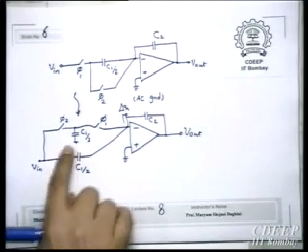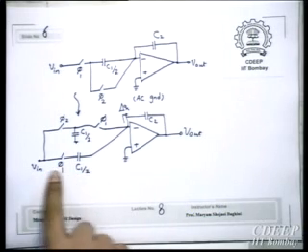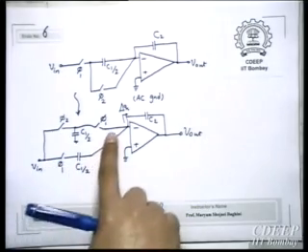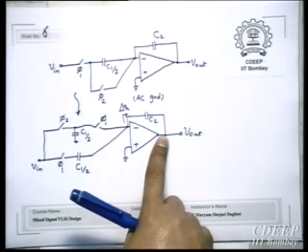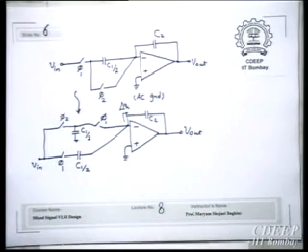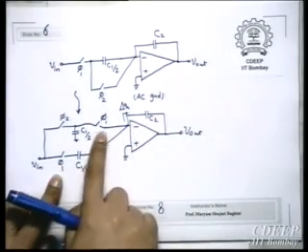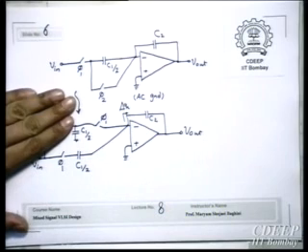Yeah. This one. Why can't we have a similar one and average the other one? No, but the point is that then we need 3 phases, because what we want to do, we want that the phase we sample, we want at the same phase to transfer it to output to avoid delay. But if you want to add this arrangement, then it means that the output needs to be revised or updated in the third phase. We want to make these two simultaneous. And in fact, even this, if you look at this part, these three are done simultaneously.